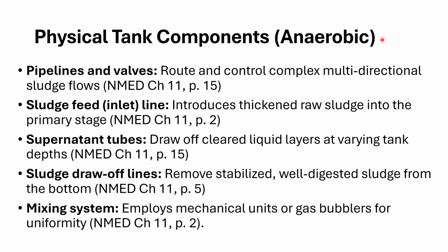So as we're bringing the sludge in from the primary and secondary clarifier, it's going to flow up, and the heat exchanger is going to flow basically heating fluid in a counter direction. It's going to flow down while the sludge flows up, so that we're heating up the sludge to get the thermophilic bacteria happy in producing, okay?